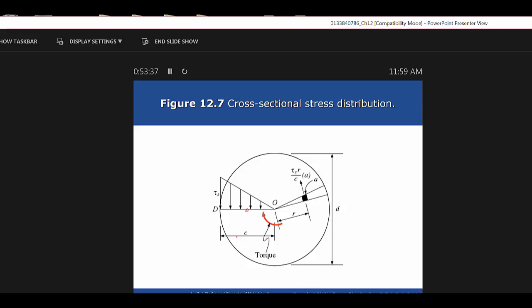Aren't you given shear ultimate, or in this case, proportional limits for shear and such on the properties back in the back of the book? So we have to make sure, if we know what the torque value is, we have to make sure we pick the right material and maybe even the right size to be able to overcome that torque value to resist that internally. So we have to work with different things as we go along here.